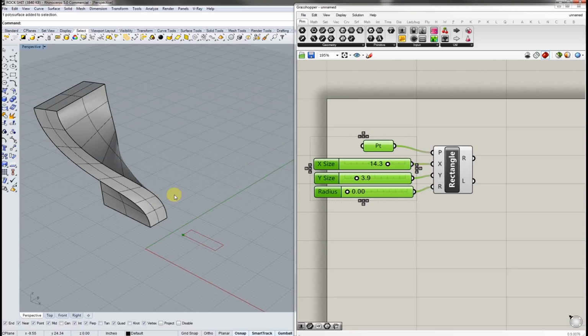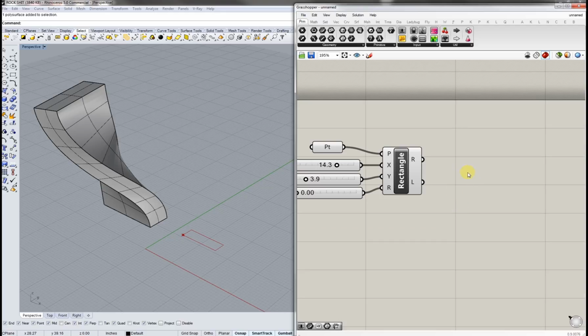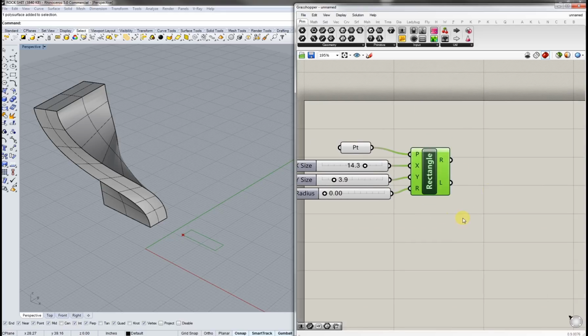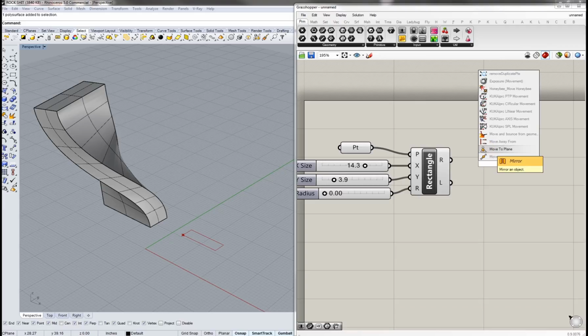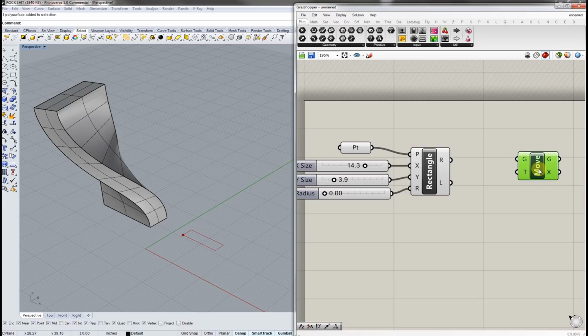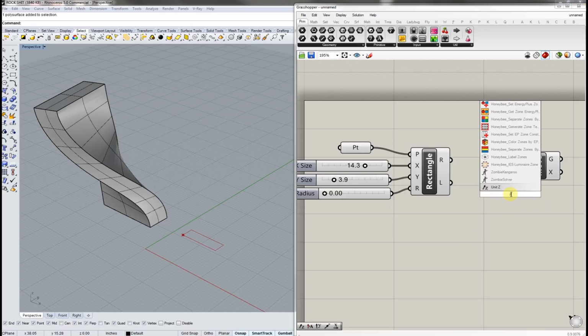This is a very, very simple version of parametricism. Now let's say we want to add a little bit of a fillet on the side. So I'll go with a lower number, 1.25. These are not accurate dimensions, so I just make that clear. As you can see, we can start to modify the fillet in here.